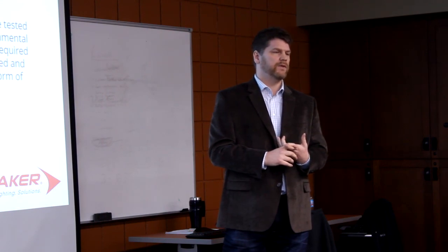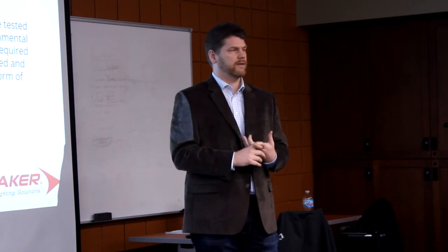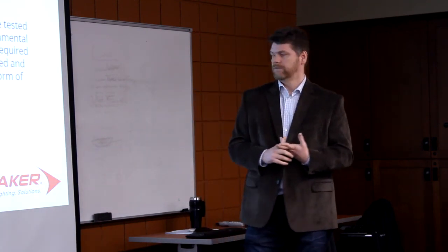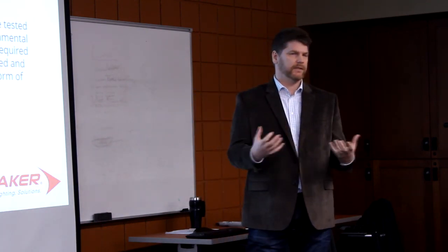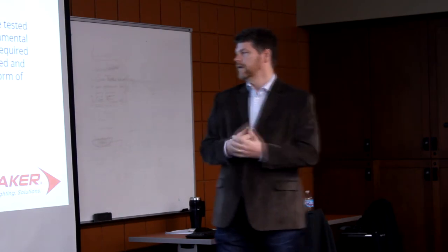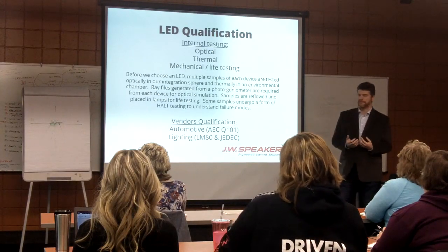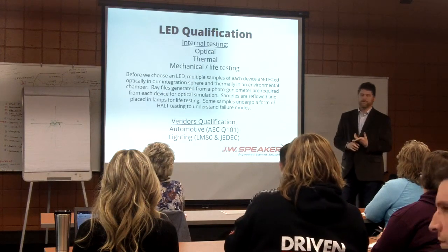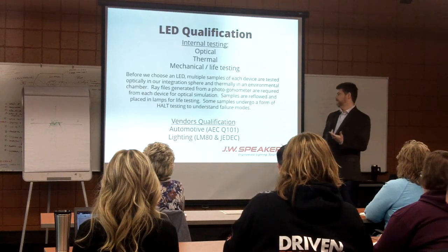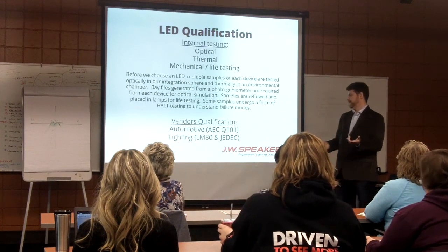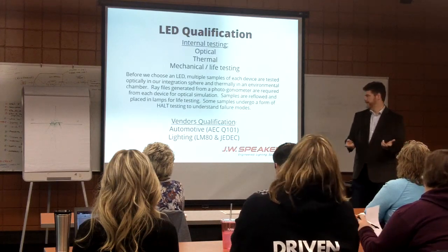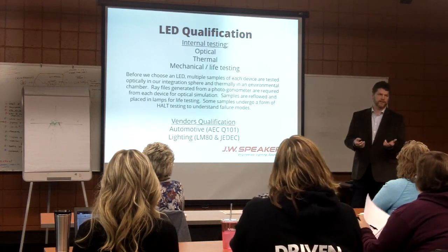And typically, other components in the lamp will be dead first, like the plastics or other electronic components. So LEDs are really tough. Like I said, they're crystalline materials. And then the vendors put it through pretty severe testing too, with either an automotive qualification like AEC-Q101 or a lighting qualification, which includes LM80 data and testing to various JEDEC specs.